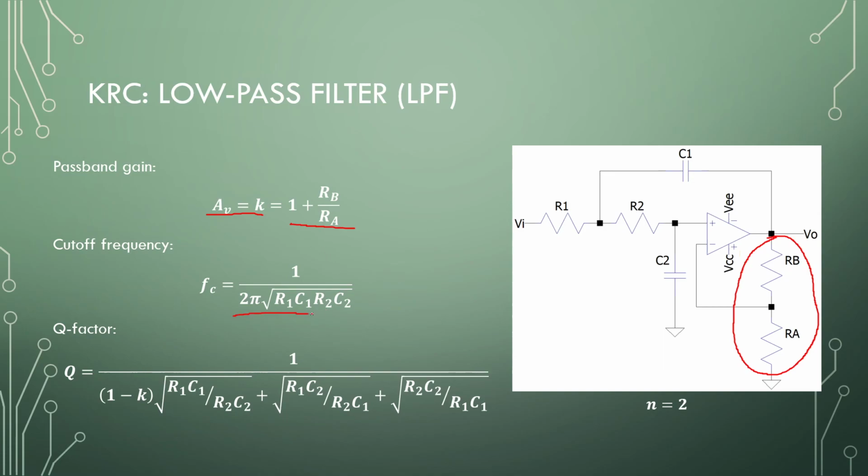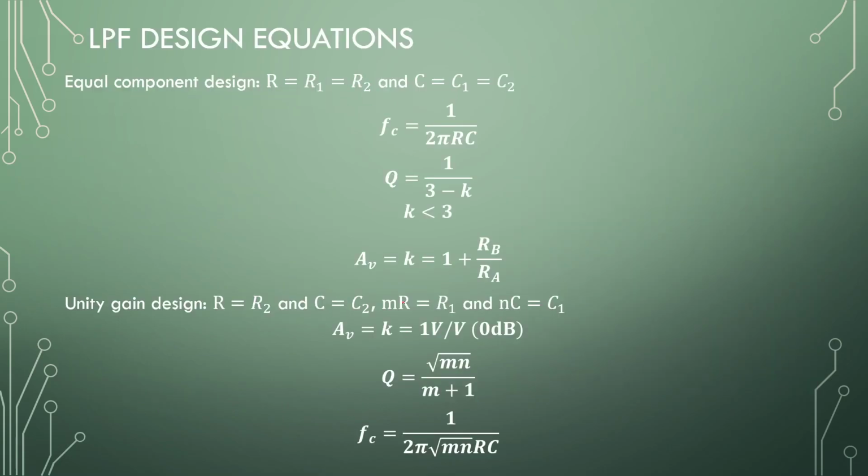The cutoff frequency is dependent on only these capacitors and resistors right here, and the Q factor is dependent on everything. But this is kind of complicated, so let's look at some ways to make life easier for ourselves. There are two methods to design one of these filters.